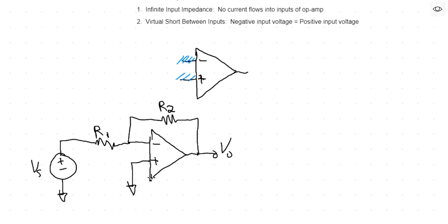So here's the op amp itself, and this is what you see here. That triangle represents the entire op amp. That's an actual device, like a chip that you would put in your circuit. And then you, as an engineer or designer, would put resistors or other circuitry surrounding that op amp, and you determine the gain that you want this entire stage to have, so that when you have an input voltage, you would get a certain multiple of that input voltage on your output over here at V out.